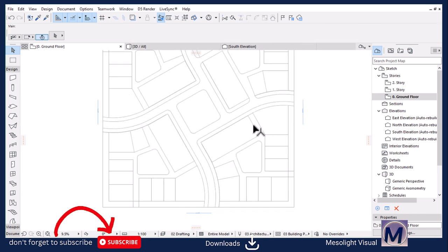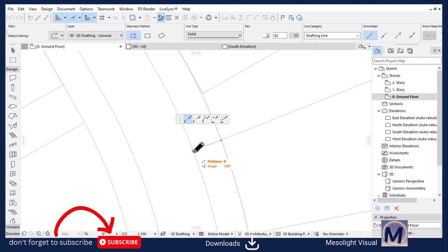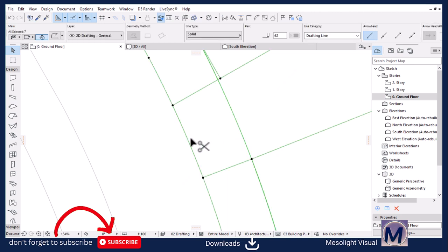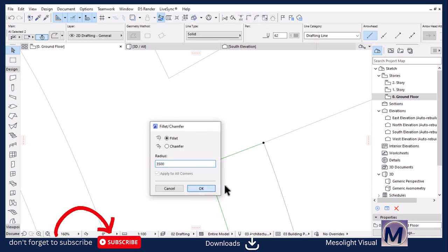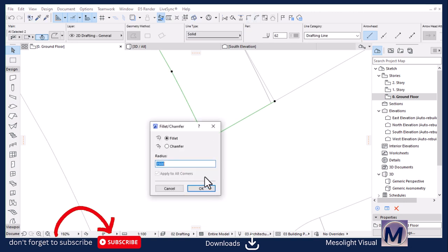This one worked without any issues. We have another situation here that needs the same approach or same exercise. Select all the lines, hold Control to activate your scissor cursor, and then fillet these corners by 3.5 radius, just like that.